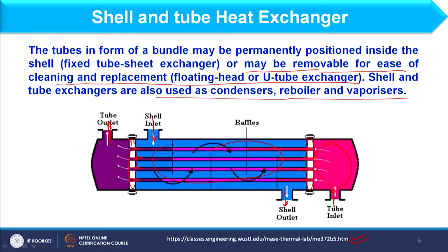Okay. Now, next we have these baffles. Okay. Some part of the baffle is removed so that liquid can move. So this baffle basically provides the movement of the liquid in the shell side, along with it holds the tube, because in the pattern the tube sheet has holes, in the same pattern the baffle has the holes, so that tube can be inserted in the baffle.